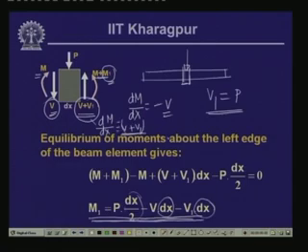Here there will be a change of the order of P from the left-hand side. So, though there is no change, or an insignificant change, in the moment value from the left of the concentrated load point to the right of it, there is a significant change in the rate of change of the moment. So dM/dx will undergo a change when you have a concentrated load, and again we will look into this through the examples.